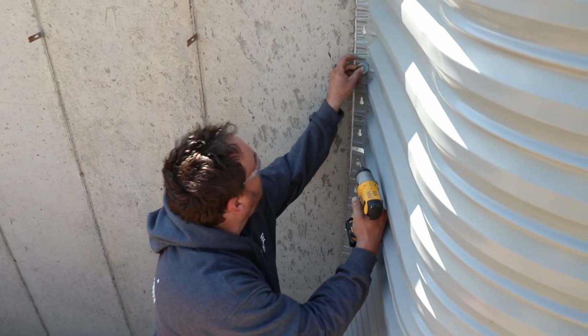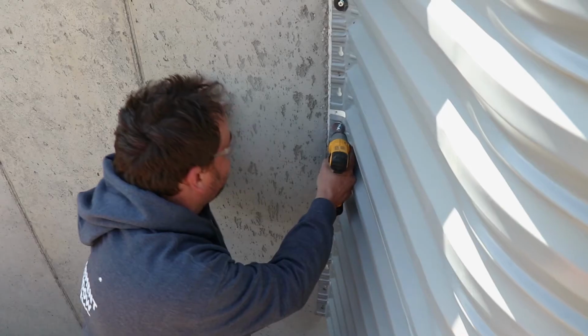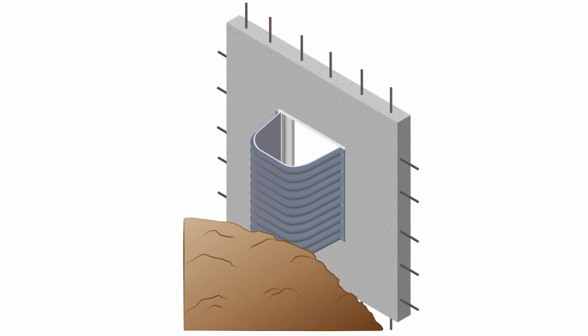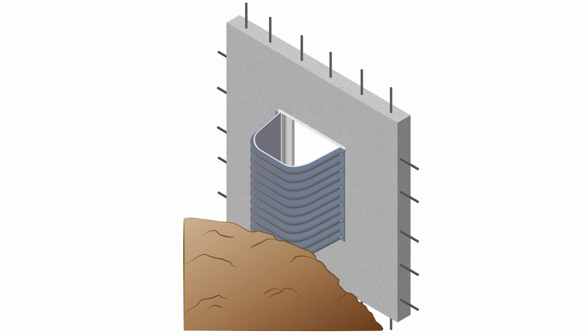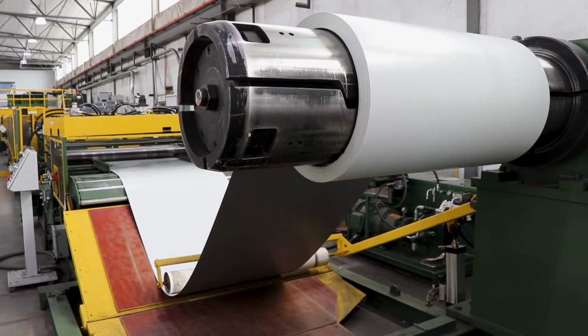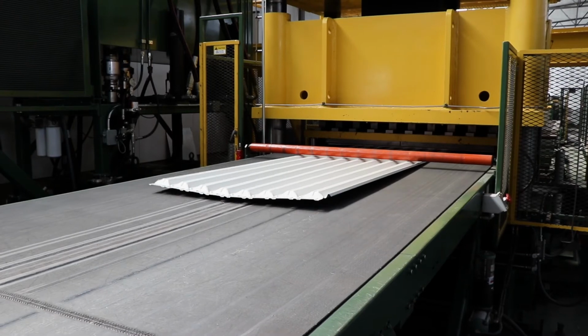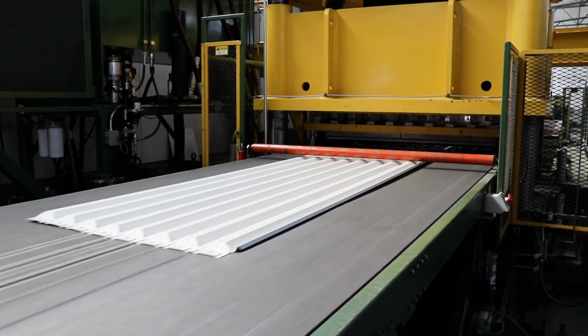The installation is complete when the area well is fully installed and the buck, attachment bolts, and area well have been tested and show that there is no connection or metallic path to the rebar. The galvanization on our area wells is sufficient to protect the area well for many years, provided that it's not part of a corrosion cell.